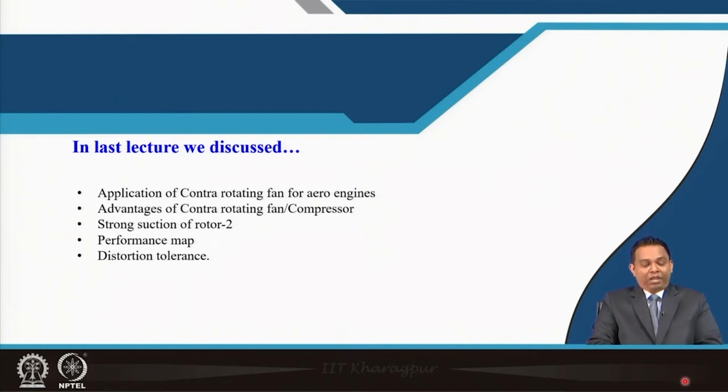Okay. Now, we have seen our own experimental results showing the performance of the contra-rotating fan, and what it says is that we have a wider operating range compared to our conventional stage. Wider operating range means my two extremes, the maximum mass flow condition and the minimum mass flow condition. We also have observed that the contra-rotating concept gives two kinds of stall, called partial stall and full stall configuration. The full stall configuration is equivalent to what a conventional stage configuration has.